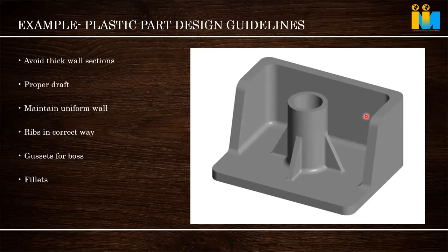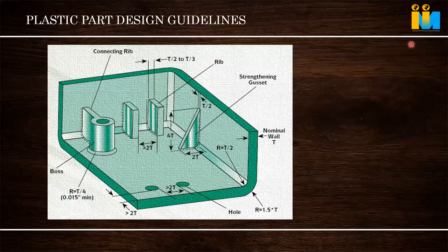Instead of giving a lengthier one, in a semi-crystalline material it tends to shrink a little more. So to avoid that, we can give a gusset like this. Or if the application calls for that area to be left open and we need some space, then it can be designed like this. I will just go through these.